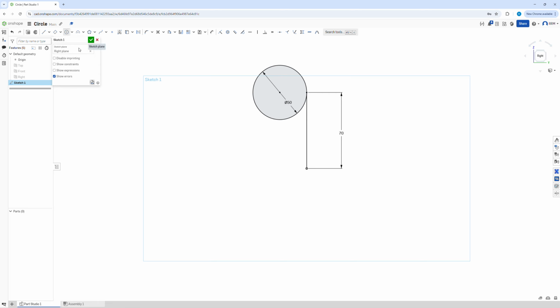Over here we have got the 3-point circle. As it says, we're going to click again, and then we have basically 2 points selected, and then we can click a final point anywhere. I could click on this bit here, and then that has also made that tangential. I can make this say 80 in diameter, and then the final thing in terms of moving this around, it's going to be able to pivot around that point because it's tangential to it. So we could maybe make this horizontal. So I've quick selected that horizontal there, and we've now got 2 tangent circles like so.